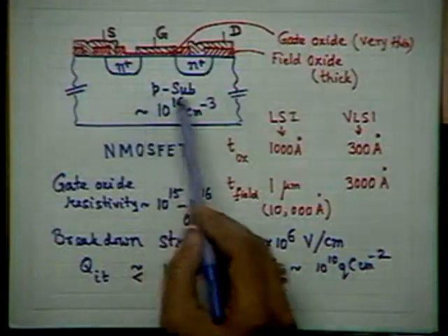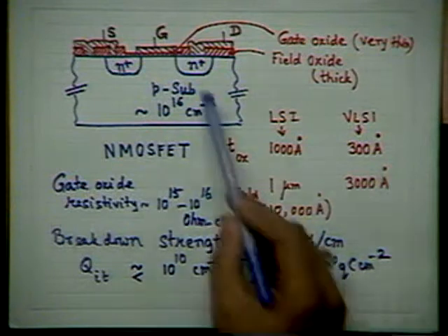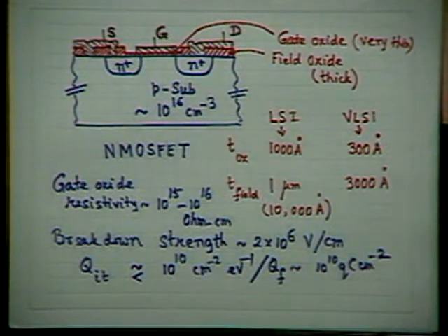Positive. So, if the substrate is kept grounded, then this junction is reverse biased. So all the drains are reverse biased junctions. These are silicon ones, and they can be of very small size. So leakage, resistance and capacitance both are very small. And there is no need of extra isolation and all these space sacrificing things. You know that automatically there is an advantage.